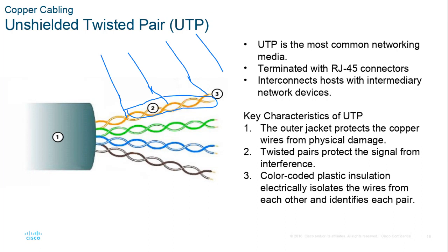There's a specific color code on all of these 8 wires so that when the technicians, the wiring guys, punch these down on RJ45 connectors, the wiring that goes hidden in the walls of the building is a standard color code. It's all wired exactly the same way. We want pin 1 of the jack to be equal to pin 1 on the other side of the jack.